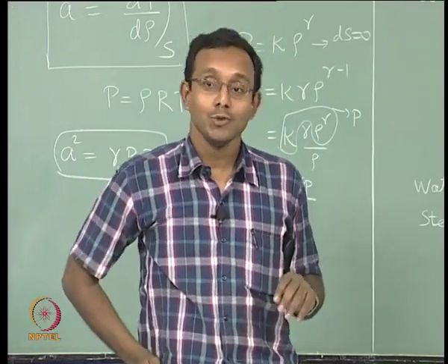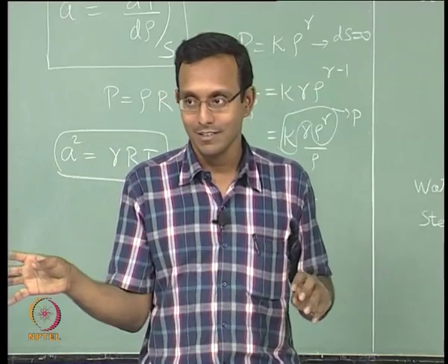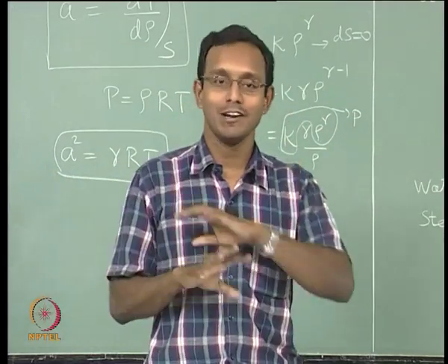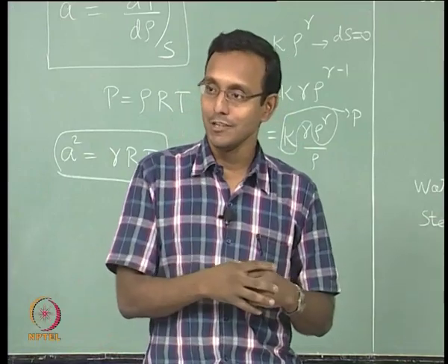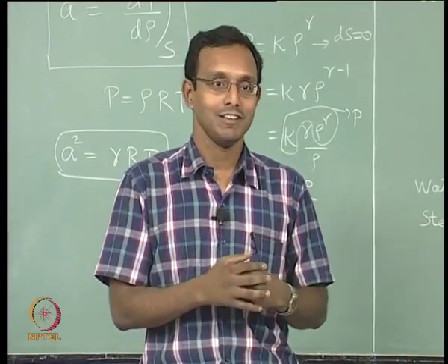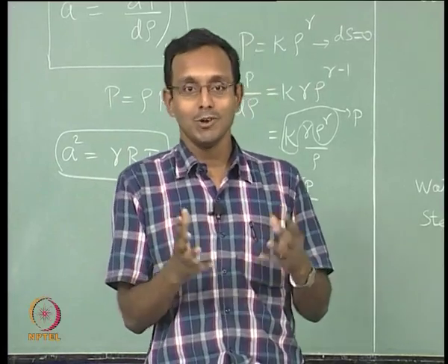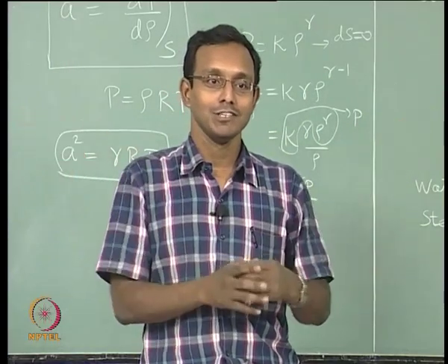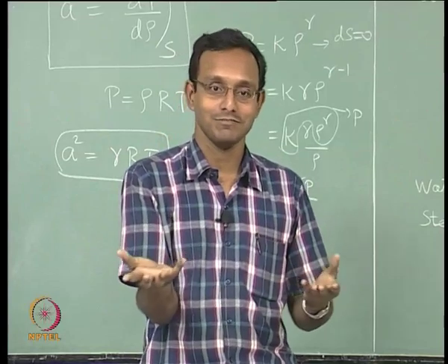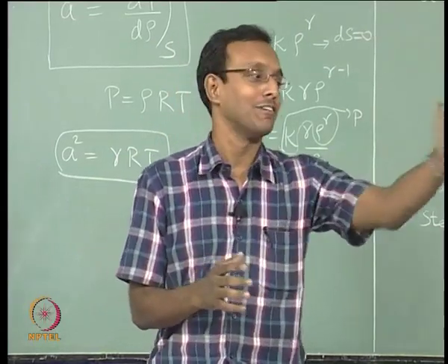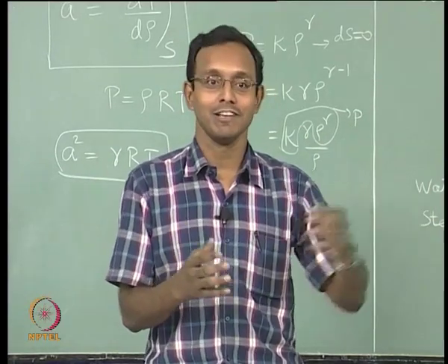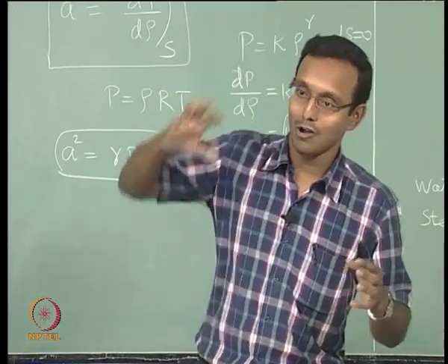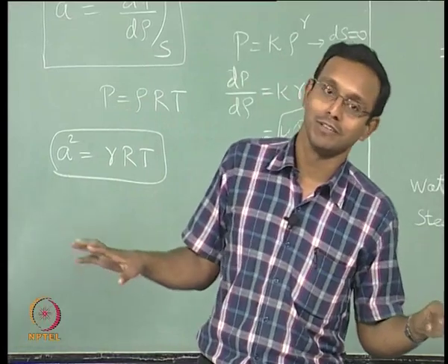It so happens that whether you disturb or not, there is always a pressure wave transported from every point in the fluid at all times in all directions. If there is a change, you will see it as a compression wave or an expansion wave. If there is no change, you do not see anything special, because it is just going to tell that single information, no change in pressure. So you do not perceive anything because there is no change. But if there is a change, you will say it is a compression wave travelling. If there is a change, it is an expansion wave travelling, you can tell that there is a change. But always have this in mind, that there are always pressure waves travelling from one point to another in the world.